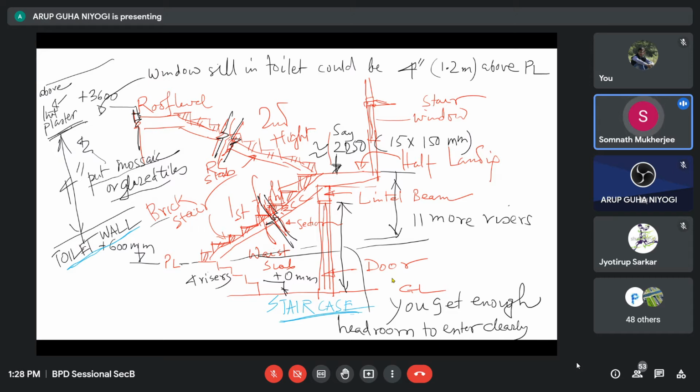You can put the sill level of your normal window at the veranda also, with the grill portion the same, no problem. But it is normally recommended to be slightly less, say 600 to 700 millimeter or 750 millimeter sill level at the veranda positions. And the gap between the sill level of the veranda grill and the floor level of the veranda is known as the dwarf wall.